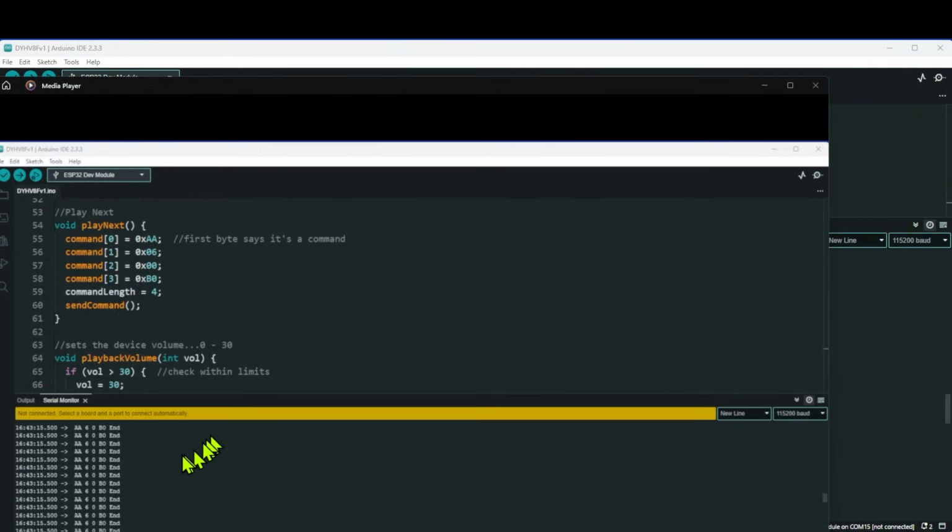Now, the issue that comes out of this is it has said here, play the next track. So the MP3 player, even before that track has virtually started playing, will read from the buffer the next command, which says play the next track. So it may take some time. It may have to empty the entire buffer, restarting new tracks, before it can actually get a track running.